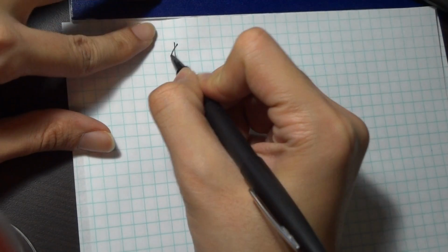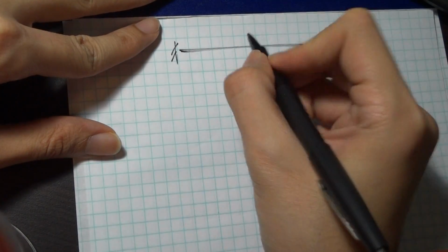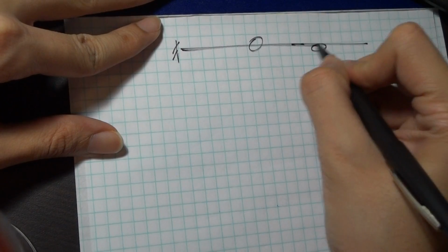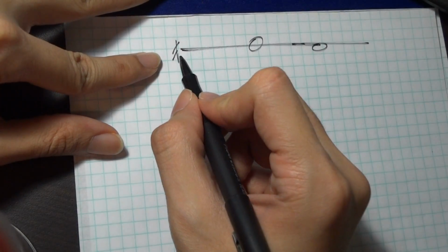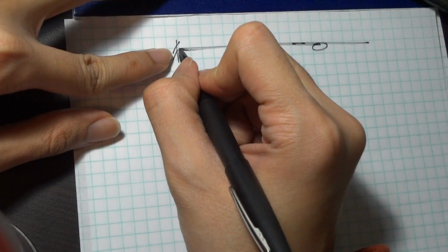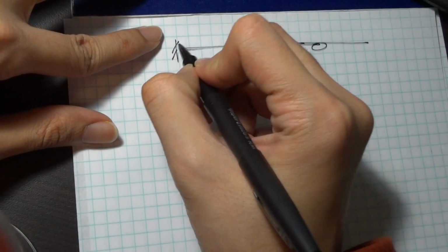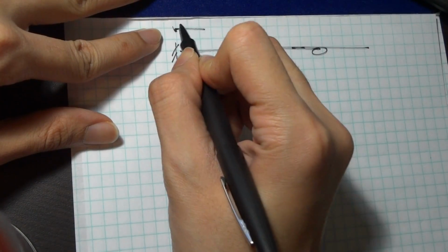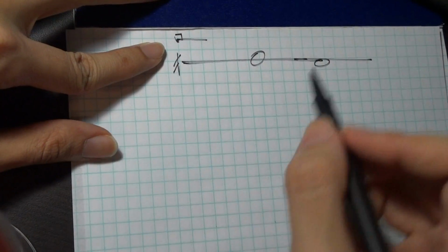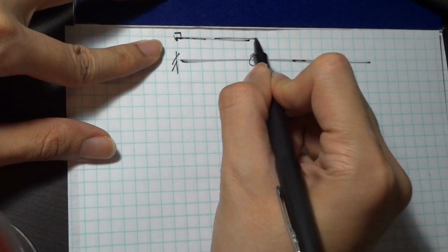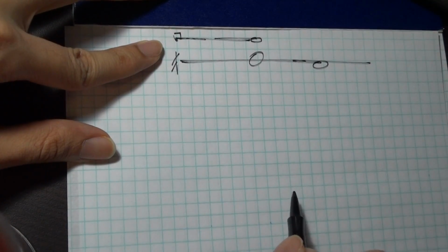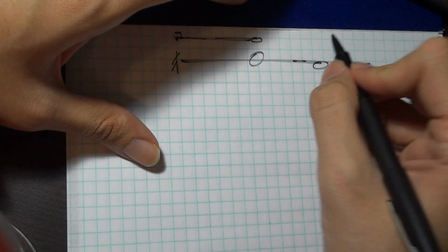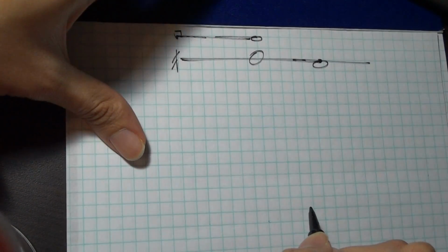So for this problem, I'm looking at first the vertical reaction, and I'm just going to draw this here for now. The first thing I want to find is the vertical reaction at A. In this case, I have a cantilever. To find the reaction, I lift this point up by 1, like so. I have to have 0 rotation here, therefore this angle is known. And I just go all the way across to the hinge. The second boundary condition I have to meet is that I have 0 deflection at my roller.